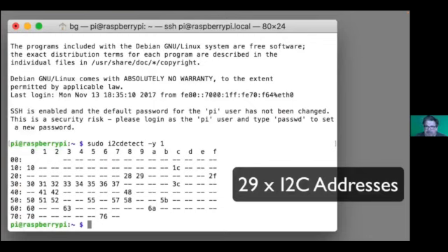The way this I2C detect works, and you can also do that in Arduino, is to go and talk to each address. And if the address doesn't respond within a timeout, then, well, there's nothing there. Otherwise, they're meant to always respond. And that's the way this works. So you can see it goes not that fast. So this was sped up a bit for this purpose here.